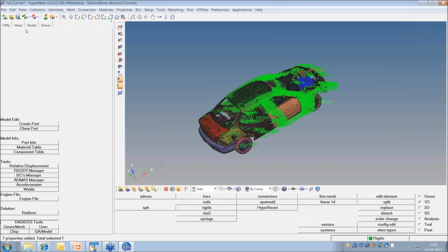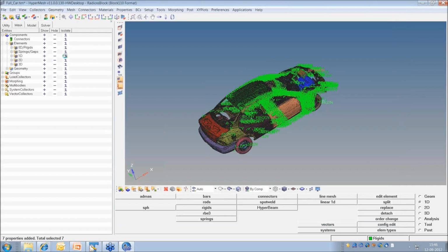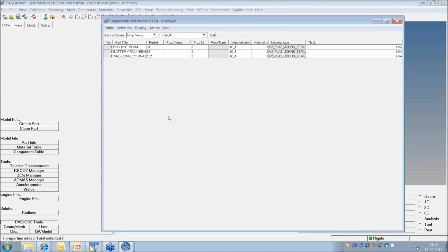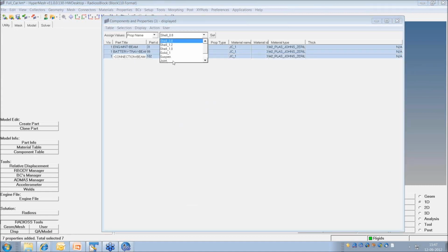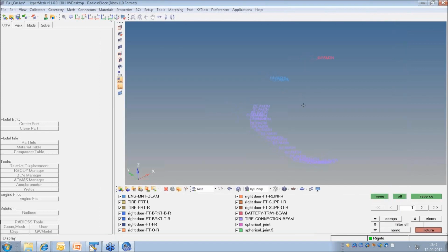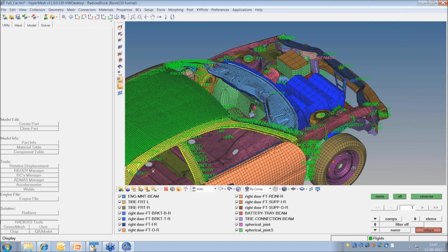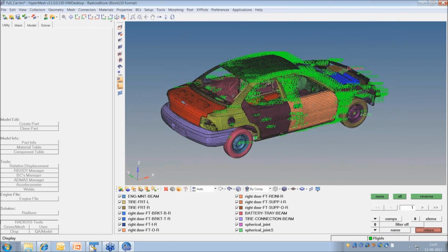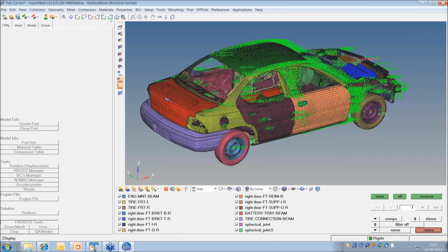property. Okay, now I again go to mask, isolate on the elements which are beams here. So utility, component table. So for these beams, property is beam, set yes. Okay, fine. Okay, so now my model is a living model which has the property and material.